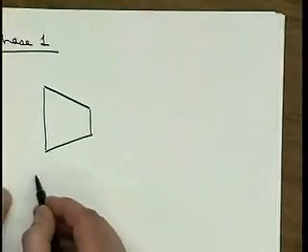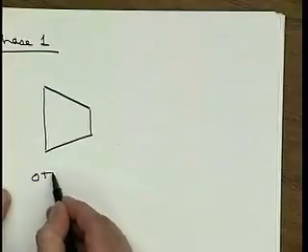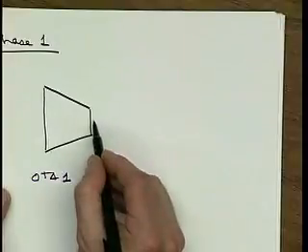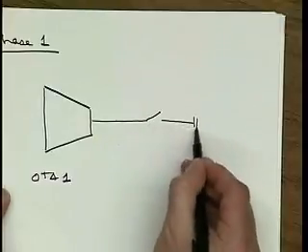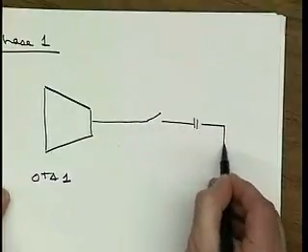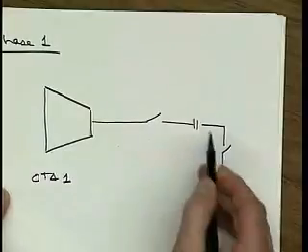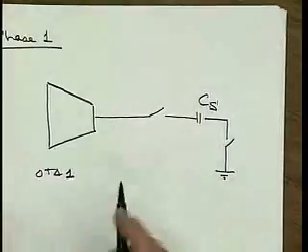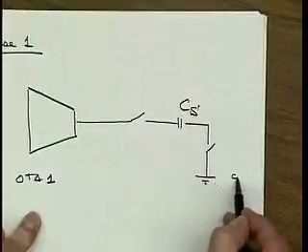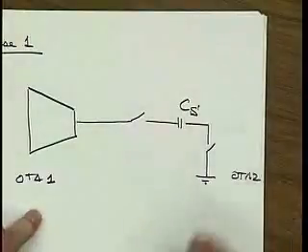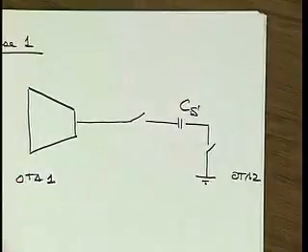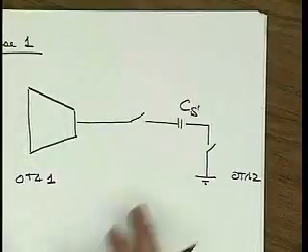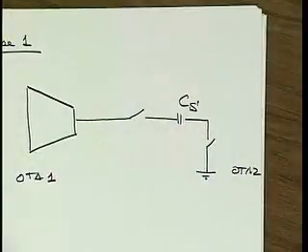There is an OTA 1 that is driving, through switches that are actually closed, capacitor CS. That's what's really happening. So this is OTA 1, and over here is our OTA 2. That's the one we're really talking about now, but somebody is driving this capacitor CS. And in this circuit, what is the noise that I'm getting onto CS?